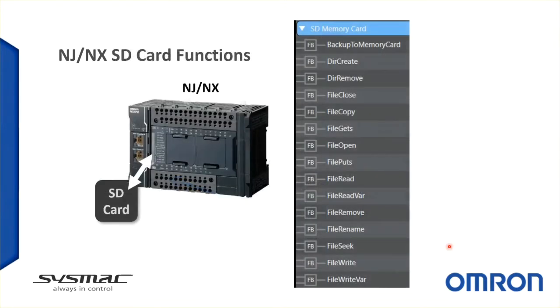And finally, the NJ and NX controllers feature a suite of SD memory card instructions to write data to and read data from files and folders on the SD card. I will use these instructions to log the KMN2 data to CSV files on the SD card, specifically directory create, file open, file seek, file puts, and file close. I won't go into detail about these instructions in this video as I want to focus on the FTP functions. However, I will show a function block that does use these instructions to log the data to CSV files.